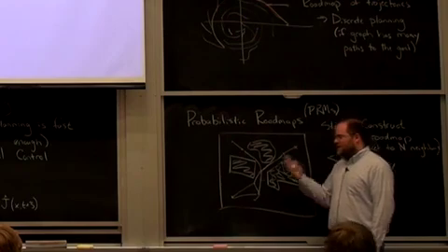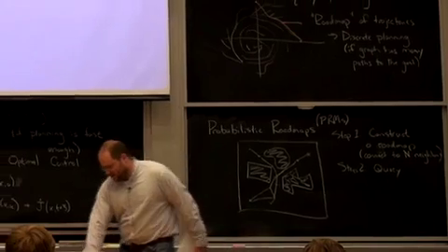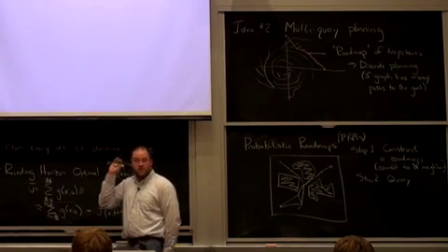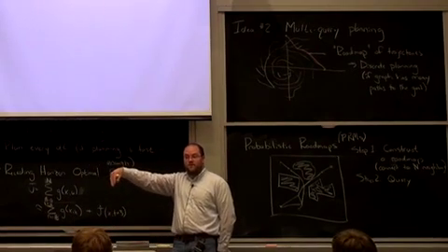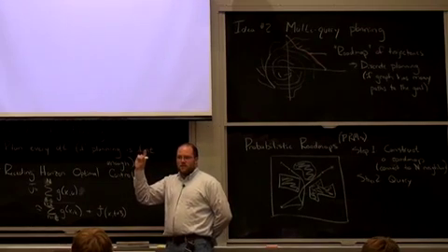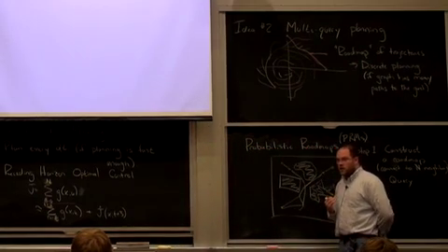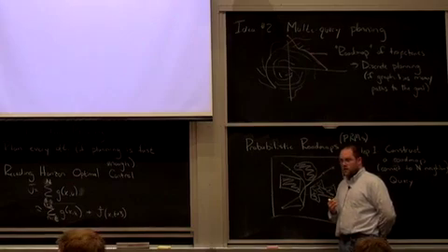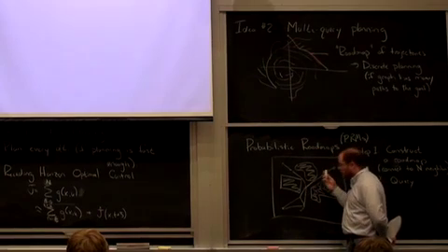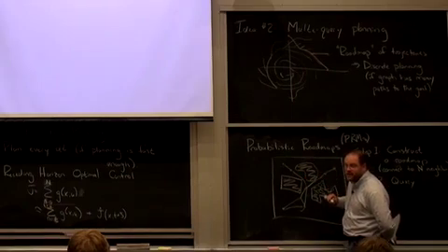Maybe my open loop trajectory optimizer told me to walk along the side of a cliff, right? And wasn't really paying attention to the fact that stabilizing that's hard. Or maybe it was saturating my actuators the entire time. That's a very real possibility, and left me no margin of control to go back and stabilize it. Didn't we take into account when we were putting those edges on that it is actually feasible to go from A to B? Yep. It's definitely feasible to go from A to B, but nothing thought about whether, if I get disturbed epsilon from this, I can recover.